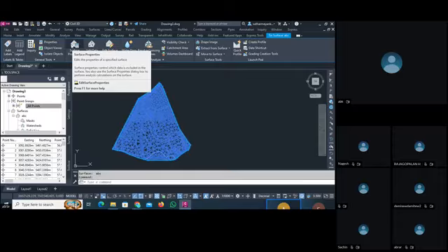In our alignment tool, we have three things: line, curve, and spiral. A line we denote as a tangent, a curve we denote as a simple curve, and a spiral is a transition curve. So remember these definitions. Whenever you see the tangent point, you have to understand that this is our line.